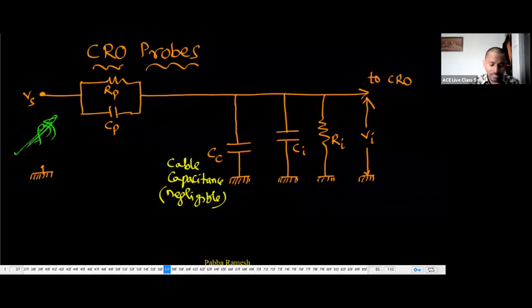As the frequency is getting changed, attenuation means the voltage drop should be the same. What must change? The time period of the displayed waveform should change. That is okay. But the voltage magnitude should be the same.